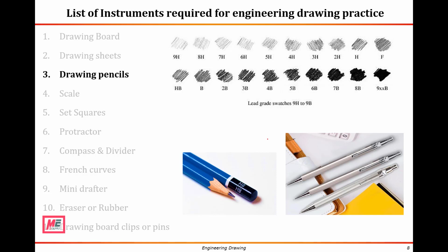There are many types of pencils in the market. Grade of a pencil lead is usually shown by numbers and letters marked at one of the ends. In the grades, the H stands for hardness of the pencil lead, B stands for blackness of the pencil lead. In the designation, higher the number before H, harder is the pencil lead. The hardest pencil shown here in the list is 9H. Hard pencils wear out less, so the lines drawn with these leads appear very light on the drawing sheet and are easy to erase. We can observe the lightness of strokes in the samples shown here.